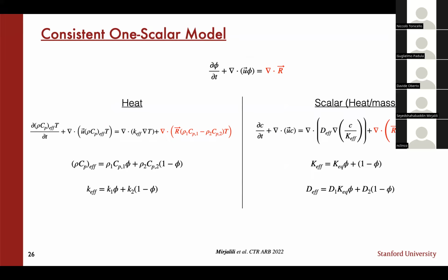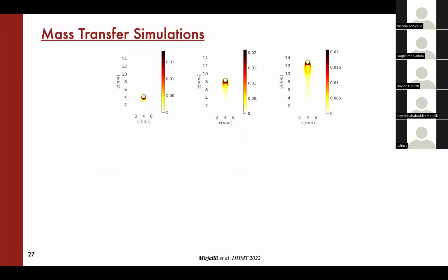If you think about that in terms of heat, for the same temperature, it's moving fluid that, say, is a liquid like water with a temperature and gas with another temperature. This movement is essentially moving heat, right? So you have a flux that is proportional to your heat capacities, right? The difference in the heat capacities multiplied by that R would tell you what you're missing, and that has to be accounted for. And the same would hold for scalar transport in general.